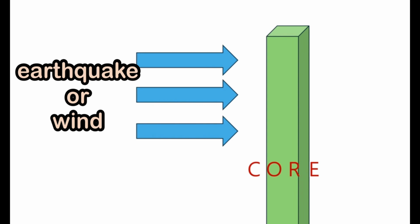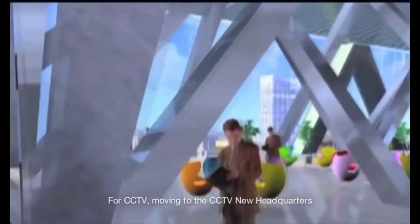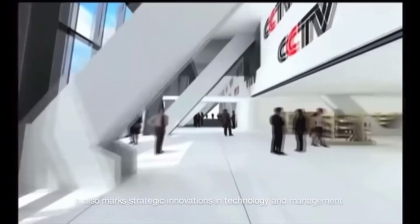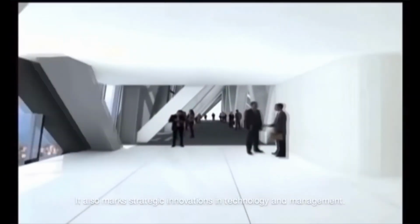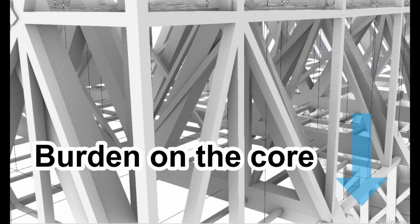Core structures are heavily burdened because they withstand most of the forces when lateral forces, such as earthquakes or winds, are at play. However, the truss acts like an outrigger to connect the outer column to the core, so that when a horizontal load is applied, the core and the outer column work together to reduce lateral displacement. This reduces the burden on the core.